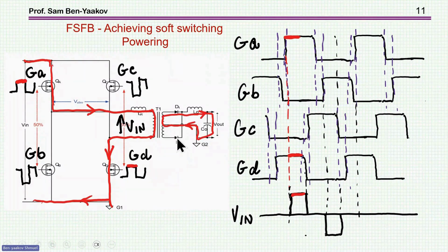Then I'm showing a diode rectifier. Obviously, you usually like to have a synchronous rectifier, but just for demonstration, that's okay. And so we have here this current going this way, and then we have the secondary, this diode is conducting and providing this power to the output, okay? And this will be when this one is high and then this one is high, okay? Here it is, this and this are high, and then you open this path here.